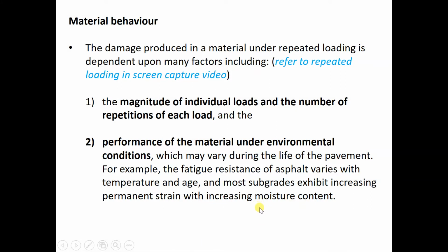And it also depends on the moisture, especially for the subgrade. If it's very wet, then the performance is much reduced, because the carrying capacity is much reduced when the ground is wet. And to a certain extent, if the pavement material as well is wet, probably the carrying capacity is going to reduce.